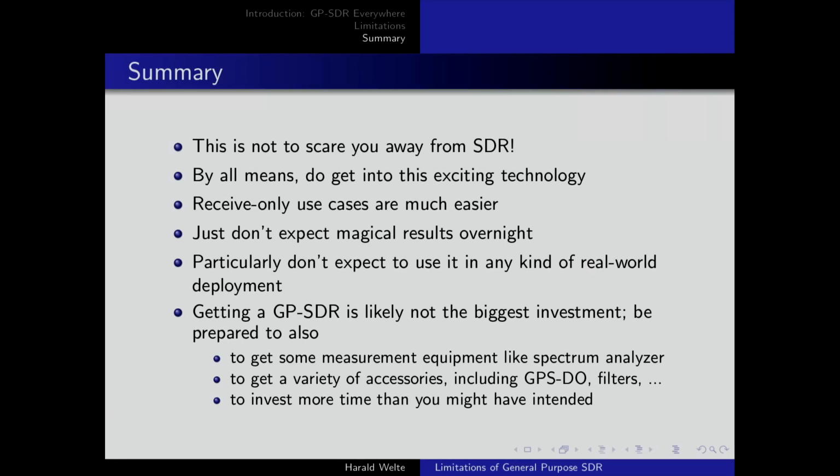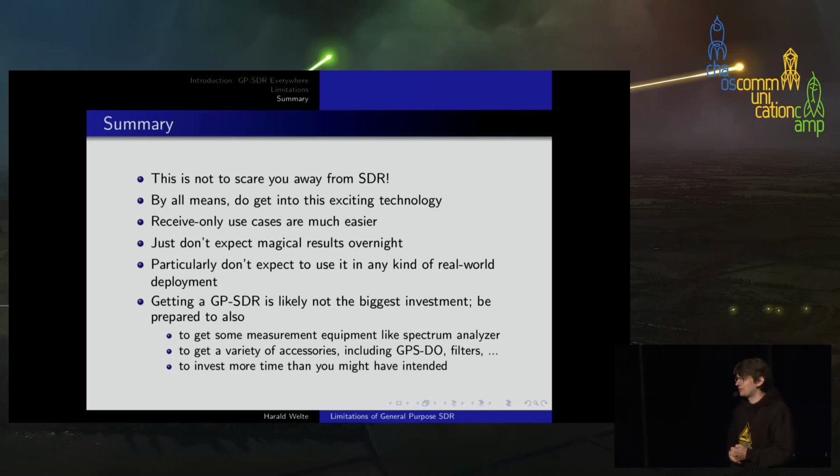And it's not as easy as just getting a general purpose SDR device from whatever vendor and then playing with software. If you don't have other accessories, like a proper clock source or a spectrum analyzer to actually look at what you're outputting, or some other tools like filters, low-noise amplifiers, maybe power amplifiers, antennas, splitters, attenuators, it's much more likely that you will end up collecting an entire zoo of devices and accessories.